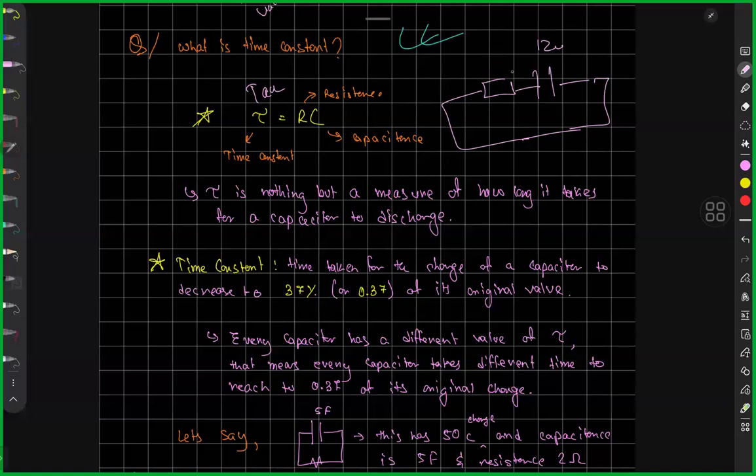When the resistor over here has a high resistance, it means more obstruction for the charge, so less charge will flow per unit time. If I have some amount of charge over here, the time it will take to discharge is much larger. That's why as R increases, tau increases, or the time of discharge increases.